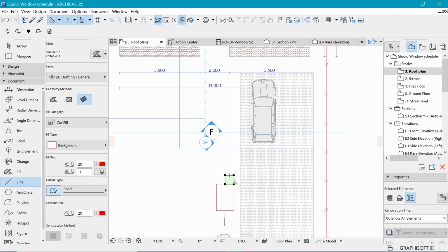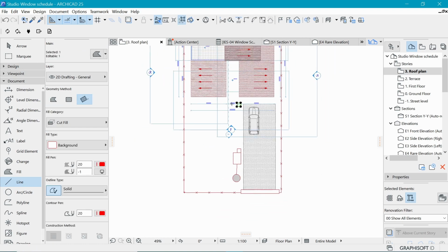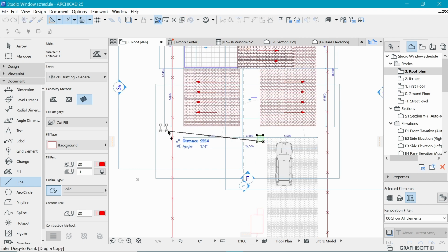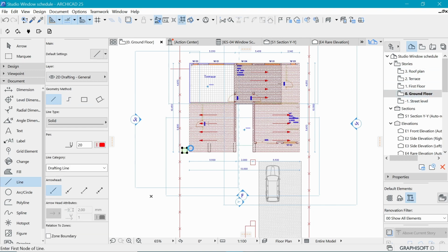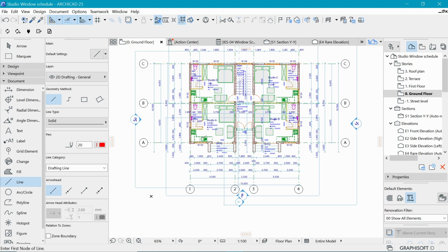And then we can go ahead and show that things leave the septic tank to the soak pit, and then we have ourselves a line of these elements that go around the building, going especially to where we have kitchen areas. So on the ground floor, you need to identify the areas where we have the kitchen, and where we have the WC, and those are the positions that actually need manholes.